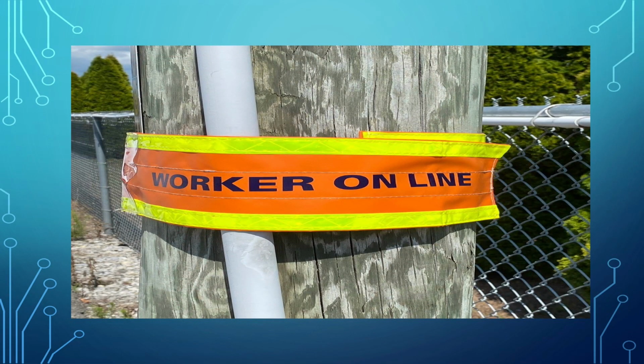With the introduction of SCADA, sometimes the tagging process may be a little harder to use. This particular item has a little place to put the tag inside. Worker on line. It's really visible at night. It's a good place, like I said, to put the tag. It's just another transfer of information to somebody coming behind us to know that there's somebody working on the line, somebody doing something. We need to contact those people. We need to definitely not make any changes to the device on the pole or in any situation until we talk to the people listed on the tag.